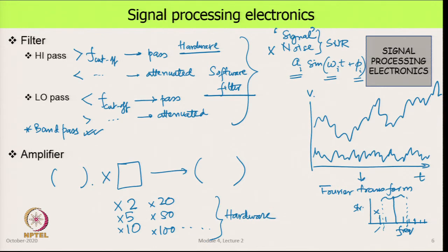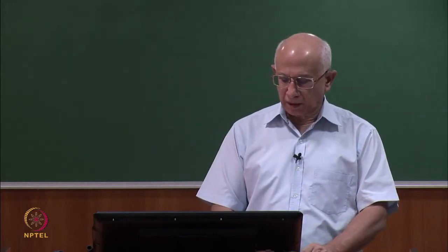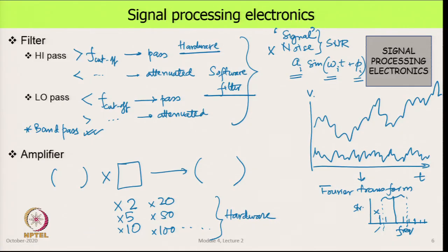And while this formula tells you that every signal will be multiplied by the same number, so that means whatever value we had, the same value in the output will be say double of that. Then at any other instant also it will be double of that. So, this is what is happening here, but that is the ideal case. Amplifiers are not ideal. There is a range over which they are linear, which means that the amplification is constant.